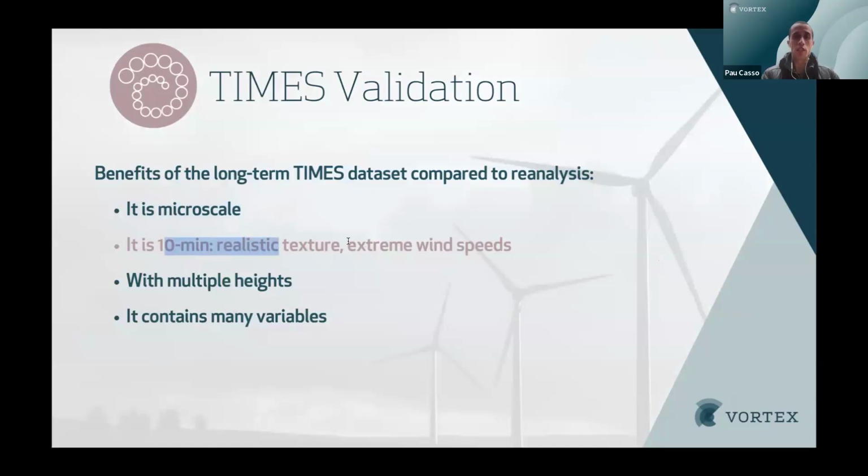Oh, let's check, for example, the extreme wind speeds, which is something that you cannot probably analyze on an hourly data set, because you really need the 10-minute thing, because it's the rule on the Gumbel fit and the standard procedure for determining the extreme wind speeds, right? So somehow you are obliged to do that on a 10-minute scale.